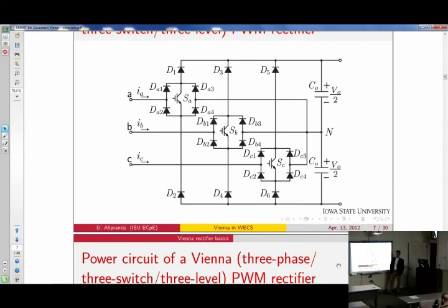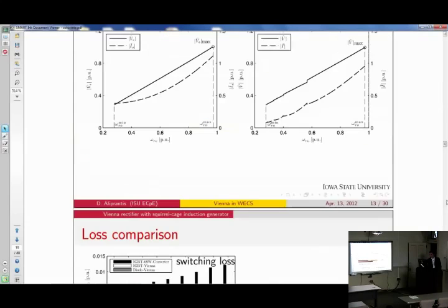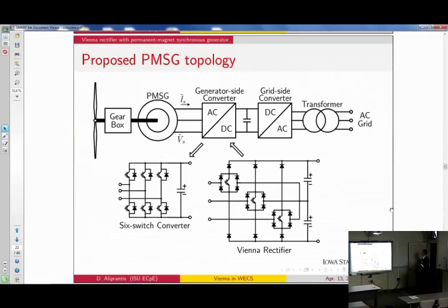What do you mean by that? You're opening a different subject. Do you mean a fault happens in the power system? Well, a nearby fault on the system, and you're trying to feed the fault current using your wind turbine. Two topics, actually. Let me clarify something here. If a fault happens here, this whole thing needs to collaborate together to handle it, and sometimes you put something on the DC link to dissipate the extra power coming from the wind turbine. So the analysis here is only steady state. We have not had a chance to look at how to deal with faults in the system and so on. Is there a plan for you to look at that? Yeah.